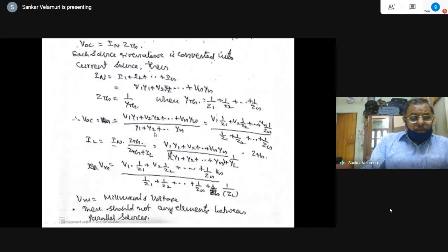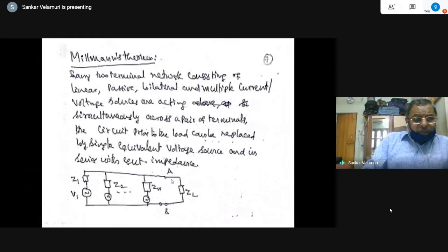I mean, everything has not been given here. Why? Because this is not the type of situation where I was trying to solve for the open circuit voltage and then find the Z Thevenin. This is the n+1 source, with the load impedance also directly taken into consideration. So there will be n+1 current generators. They use the term current generators.